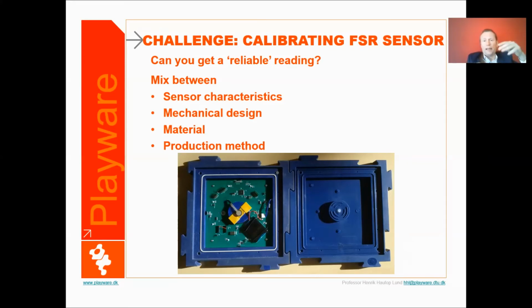And I said the mechanical design, you see on the image around the electronics on top of this blue PVC, there's this O-ring, the white ring going around that gives some kind of flexibility, some spring quality. Also around the sensor, you see we have this kind of double tape around the sensor, so that's also flexible, giving some spring quality. On the right side, you can see the next prototype round.